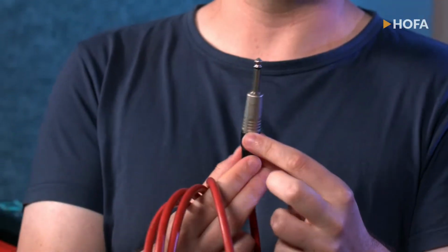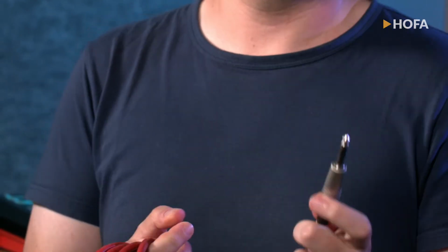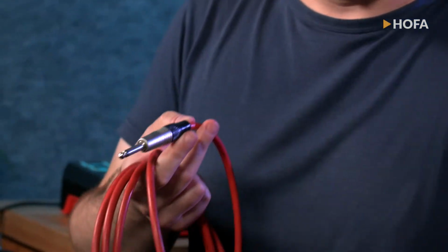That's for sure all possible, but we'd recommend, if you have a lot of length because of distance, maybe on stage or in your studio or in your recording setups and surroundings, you might either use something like a DI unit, for example, to balance the signal, or at least at one point, a balanced connection. So that's an unbalanced connection, so we only have one tip, and ground or shield. If there is noise and if there are any things that might disturb the audio signal and affect a clean signal flow, this might happen, especially when the cable length is far too long.